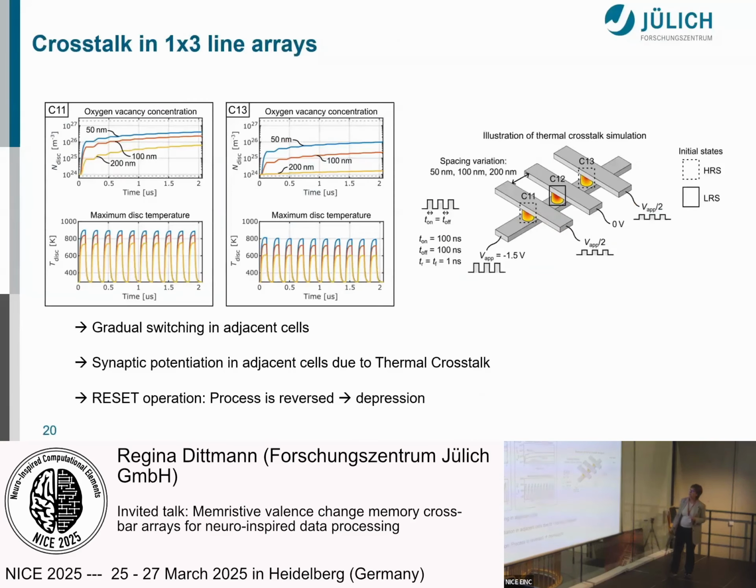So here are some simulations of the temperature and the oxygen vacancy concentration of two memristors next to the selected memristor, which are half selected.